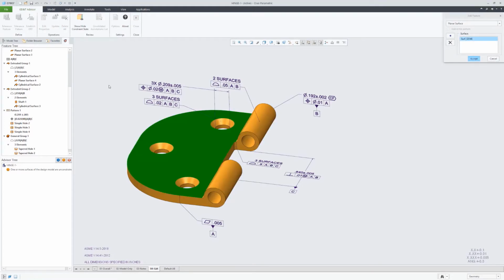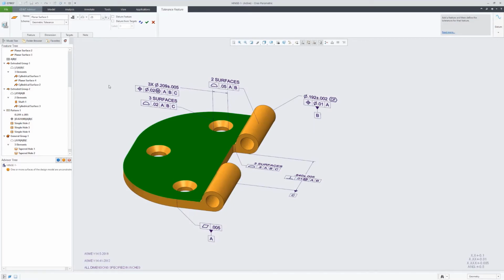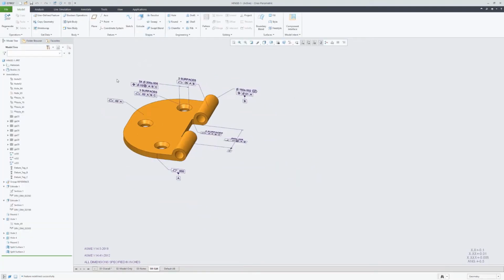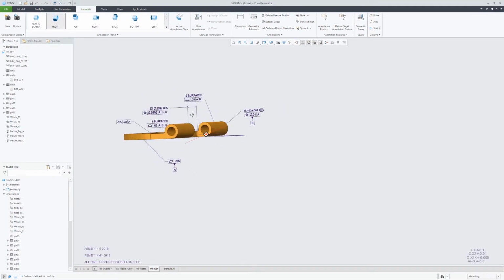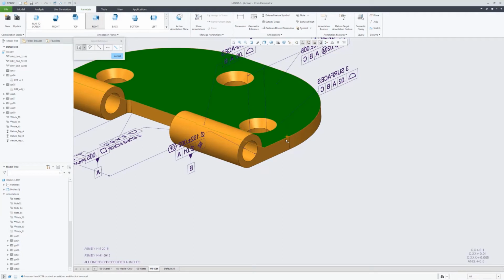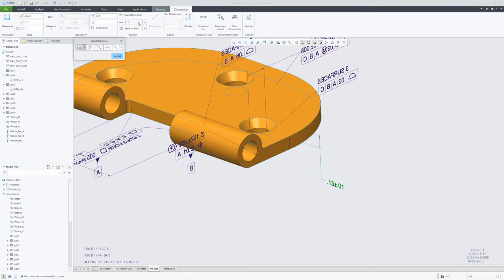Next, we will tolerance the top of this hinge plate. So it recognized that as a planar surface feature. There again, it's recommending a surface profile tolerance to be used here. And that one, actually, we're just going to the datum reference frame of A, because we're really only interested in its relationship to datum feature A, which is really going to control the thickness of that plate. So that we don't have to have a consumer query the model to find out what that thickness is, we're going to go ahead and add a basic dimension here to give you that information.